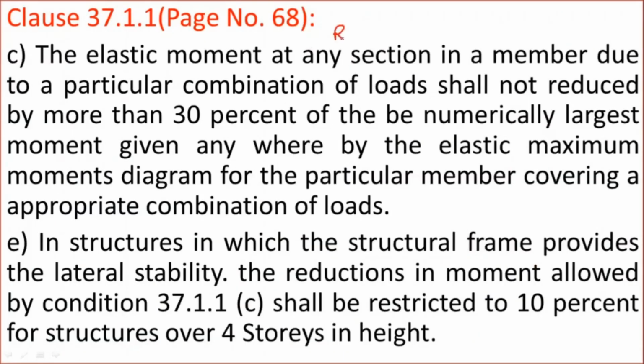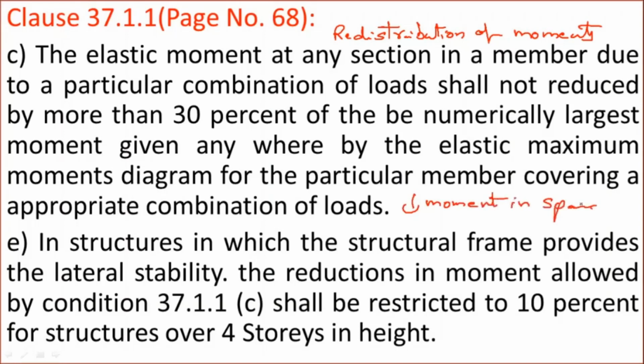The next clause is related to the redistribution of moments. This concept of redistribution of moment is related to the plastic analysis. Because of this redistribution of moments, the advantage is that the moment in the span reduces, as well as the moment carrying capacity of the structure increases.